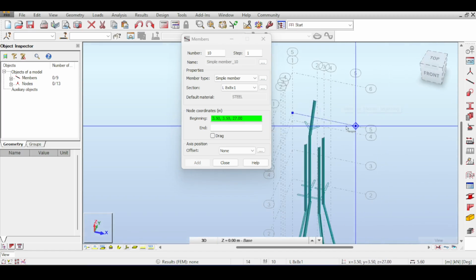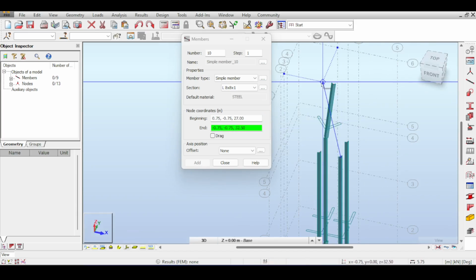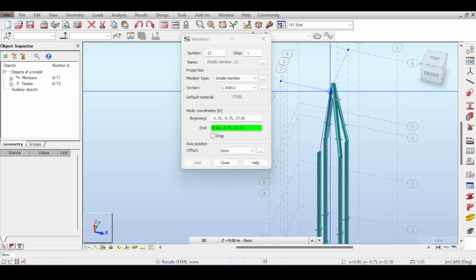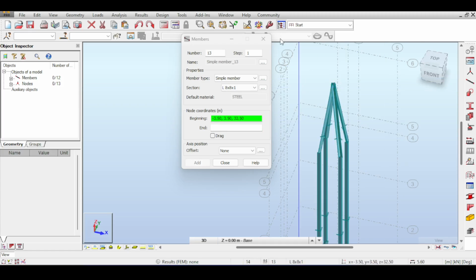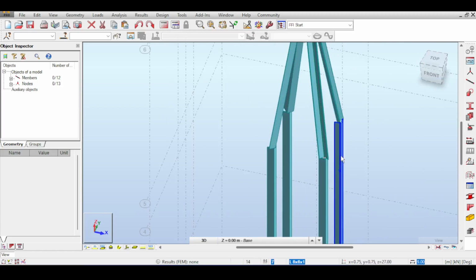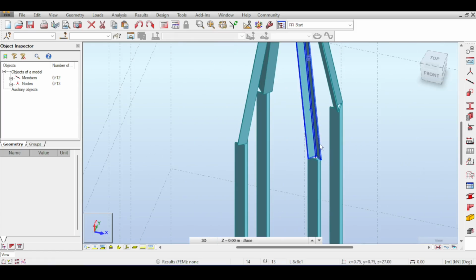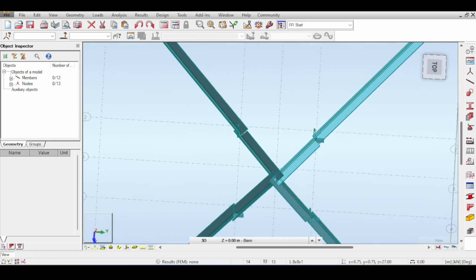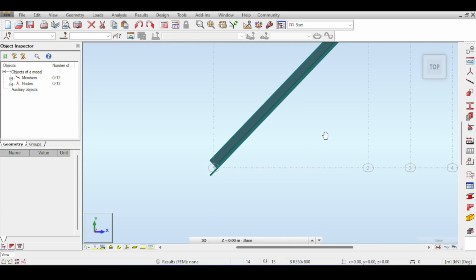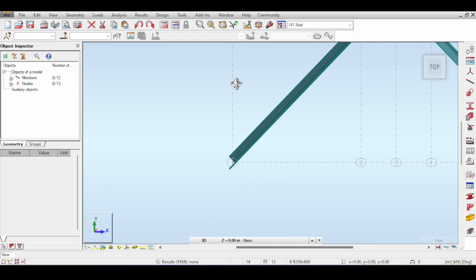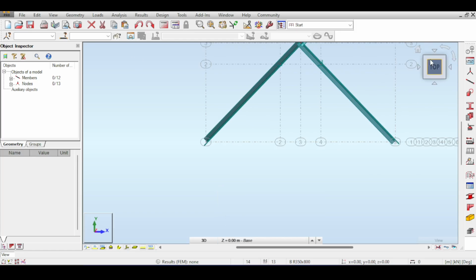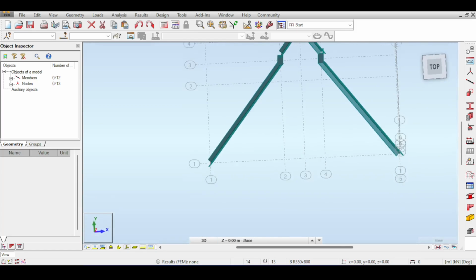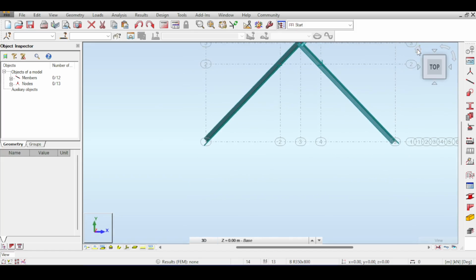Okay, so the rest is easy because I now have a point. I can easily just connect those things like this. Notice once again, my sections have a very strange gamma angle here, like this. This is not what you see typically. No, this is beyond ridiculous. So going on with this, let's change the gamma angles that we have here, because those angles should be pointing inside, or at least partially inside the structure. Those angles are not correct, so they need to be corrected.